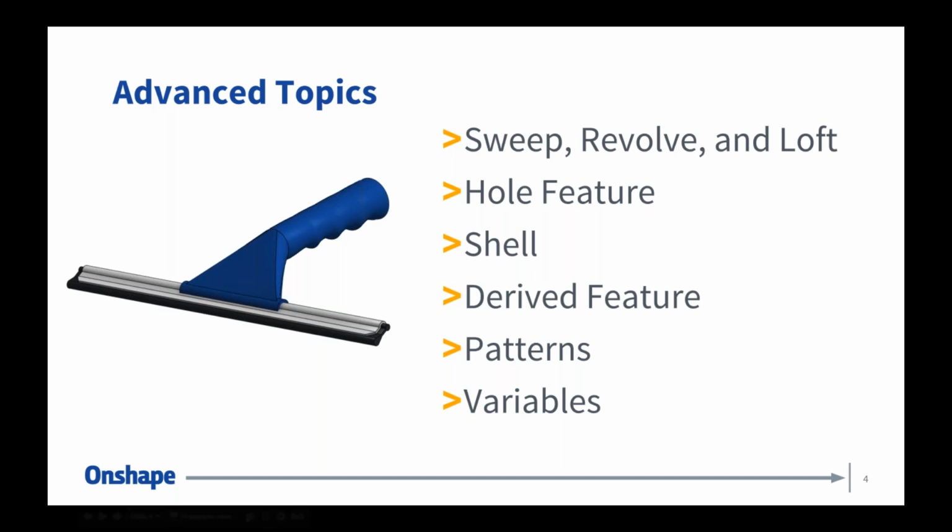Question: I am doing a simple bearing that I want to use in multiple places. What is the best way to do that? If you're referring to the organization of it, I would put the bearing in its own document, reference it, you can version it, and then insert that bearing anywhere you want.